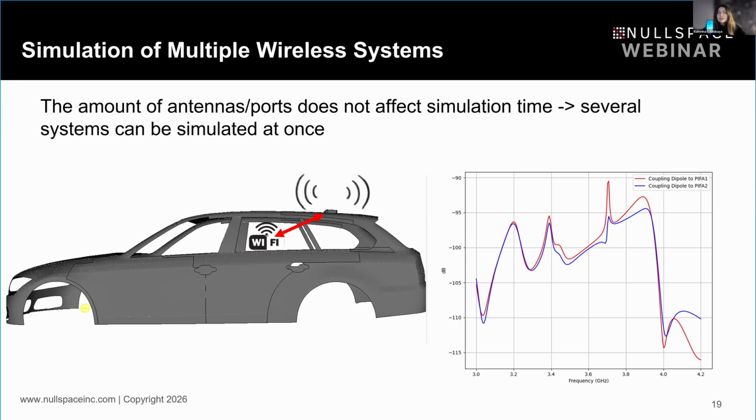It's not the same frequency, but sometimes in our antennas we have parasitic resonances, we have radiation peaks that we don't expect, and they can happen on frequencies that we maybe didn't even think about, and then there is some big coupling happening. So that is very good to consider as well. Here we simulated coupling between our antennas, and you can see it's very low. It's virtually non-existent, and that is very good. But it's something that you really need to control as well.